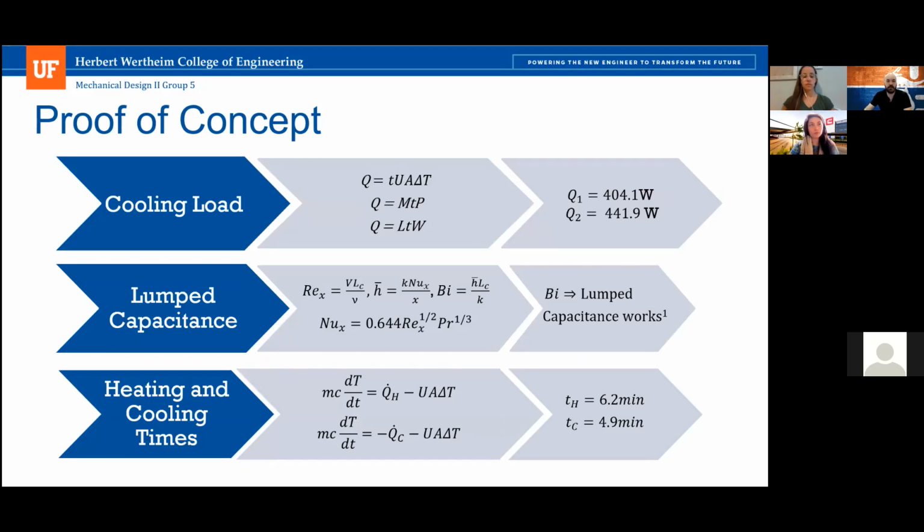First of all, the cooling load calculations were done by treating the chamber as a cooling room. Several factors were accounted for, including the heater fan motors, the shaker motors, the liquid handling motors, chamber volume, and the LED lights installed for photosynthesis, and the LEDs for the ODFI section were considered when developing these calculations.